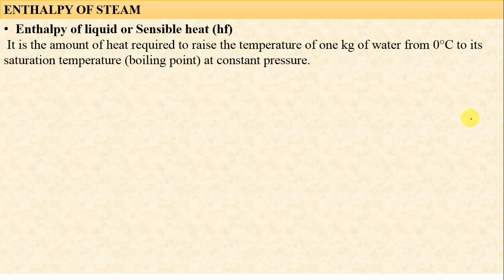Now we will discuss the enthalpy of steam. There are different types of enthalpies of steam. First is the enthalpy of liquid, or sensible heat, Hf. It is the amount of heat required to raise the temperature of 1 kg of water from 0 degrees Celsius to its saturation temperature at constant pressure. We call it Hf.